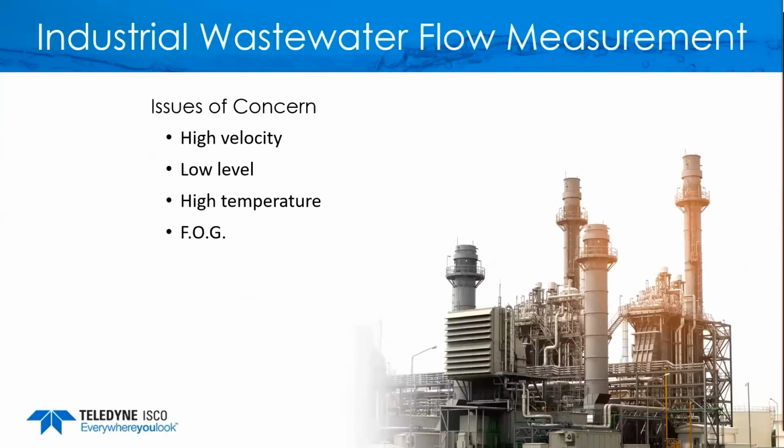Now, some of the concerns for industrial wastewater that's a little bit different than municipal wastewater is that municipal wastewater is usually fairly consistent. It's a little bit lower in the mornings, higher in the mornings, and then lower in the evenings. But with industrial flow monitoring, you can have high velocities, low levels, high temperatures, fats, oils, greases, depending on what's going on.